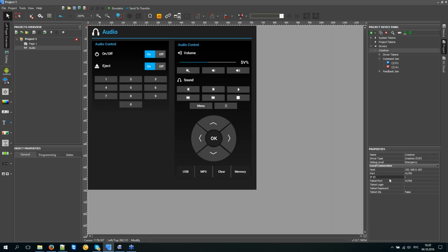The very important parameter is the IP ID. You have to copy this IP ID from the Crestron project. You set it up for XPanel. You set it as a hex value, for example 03, but in iRidium it is a DEC value, decimal.